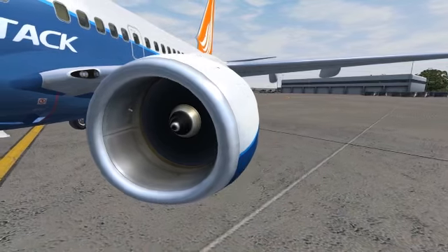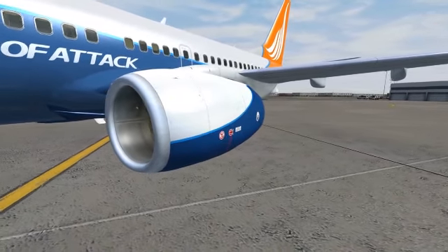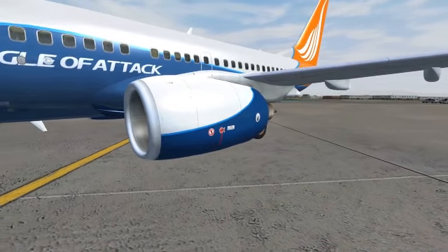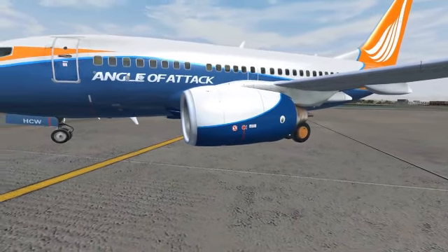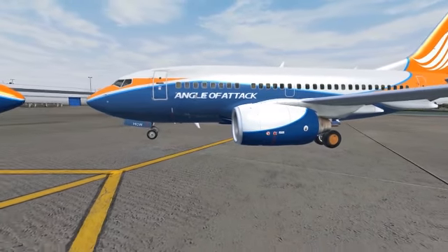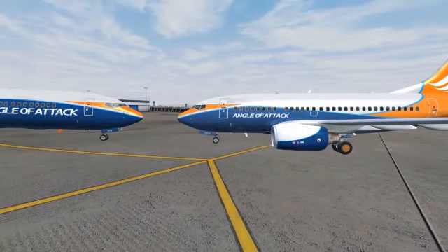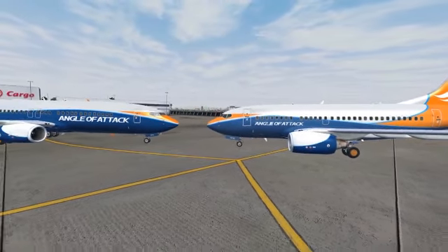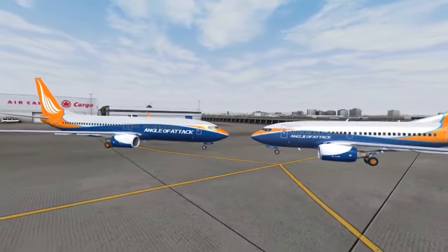The answer is yes. However, each individual aircraft type, like the 737-600 or 737-800, has specific thrust configurations and a maximum thrust setting that is outlined and configured with an engine identification plug that specifies each thrust rating for each individual variant of the 737NG.